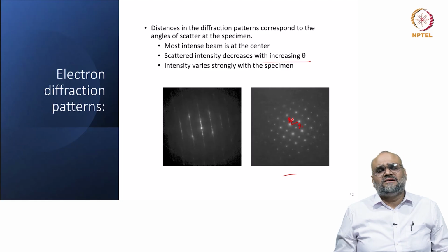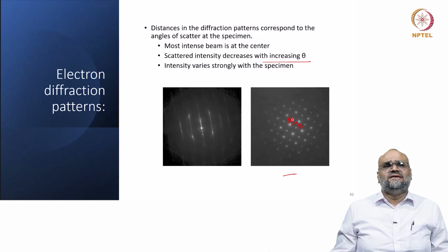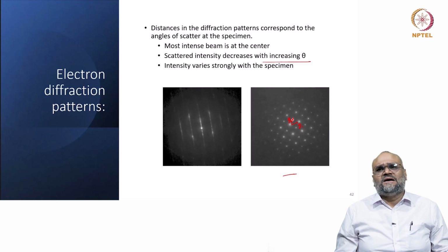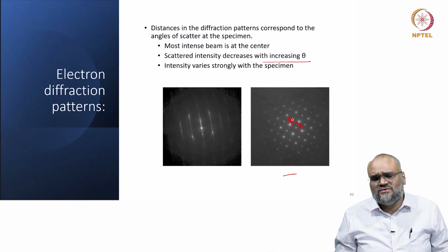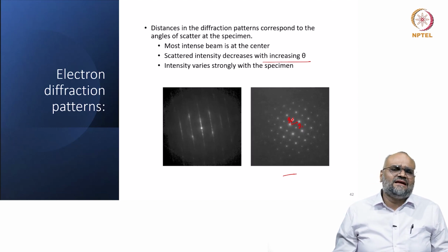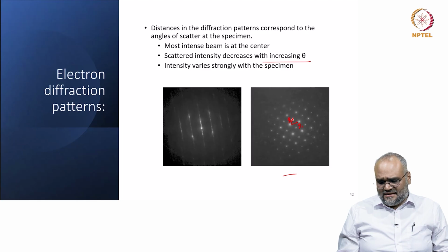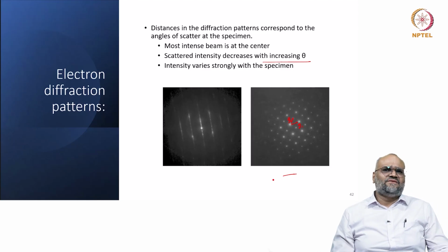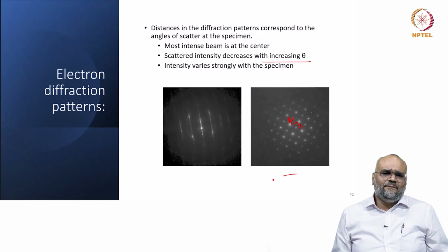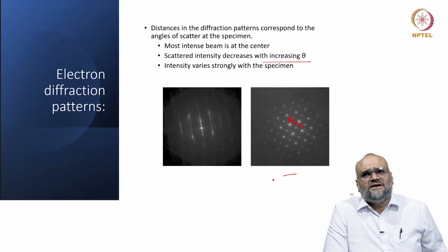When I talk about solving the crystal structure and obtaining crystallographic information, I would say transmission electron microscope is extremely important to understand the symmetry, the positions of the atom and the crystal structure information, but it is a very localized technique. Often complementing this with an X-ray diffraction study gives you the complete information on crystallography from a material.